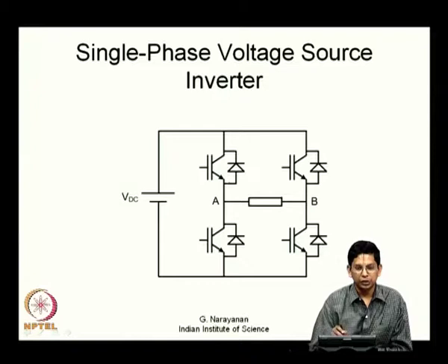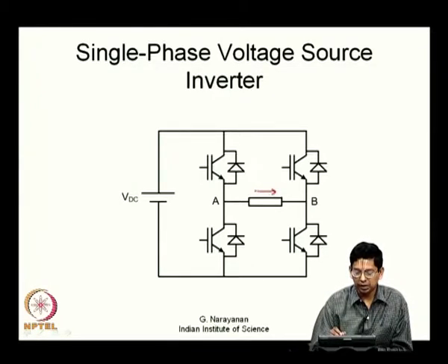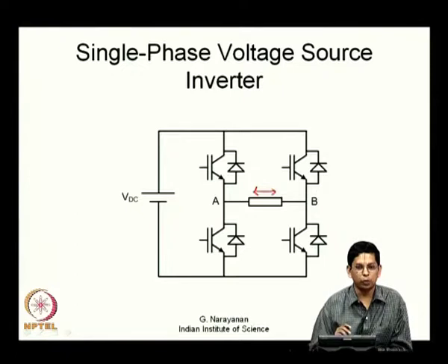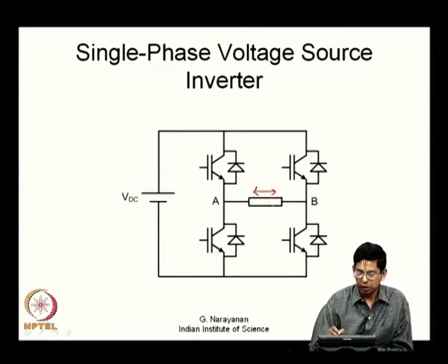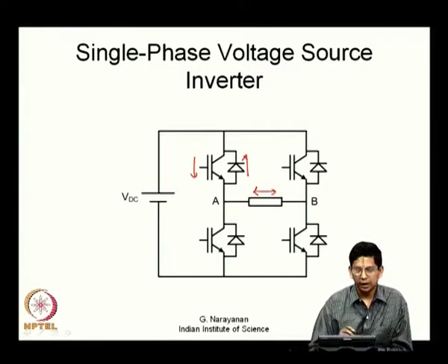What you do is you can have a switch like this. So, you can have a bidirectional conduction here, in any direction the load current might be flowing. So, if the load current is in one direction, the transistor will conduct. If the load current is in the opposite direction, this diode can conduct. And let us say this switch is also on. Correspondingly, depending on the load current direction, the transistor will conduct or the diode will conduct.